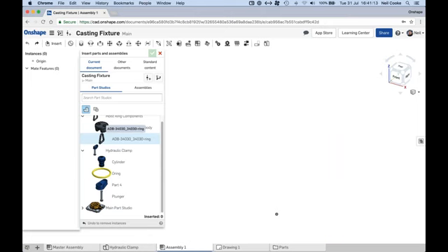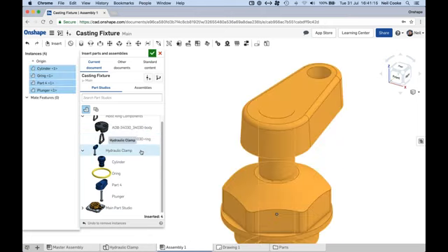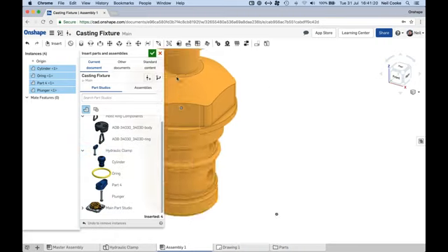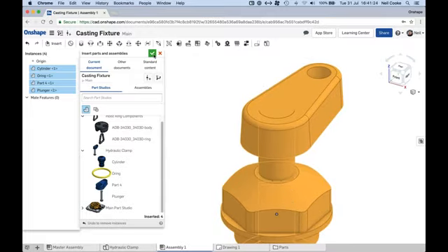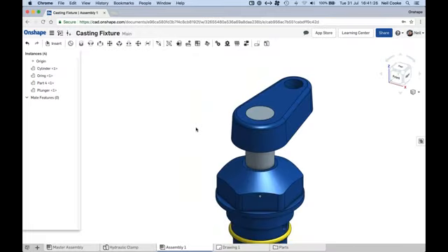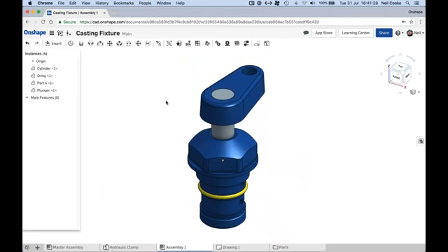However, you can treat a part studio almost like a subassembly by clicking the actual name, and it will bring all the parts from that part studio into the assembly. Now you can place that, or you can just press the green tick, and it'll position it relative to where it was in the part studio, which in this case is around this origin here.